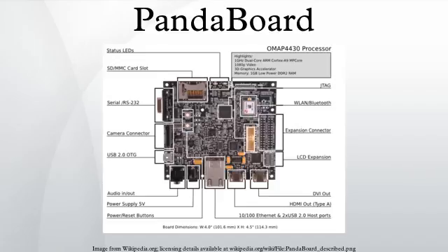The situation for Linux X11 utilizing hardware floating point libraries is that PowerVR's SGX 540 GPU hardware is unusable without a GPU driver. Furthermore, PowerVR will not release documentation so that an open-source driver could be produced. This all adds up to the GPU hardware being unavailable, so the above-mentioned features of course will not function.